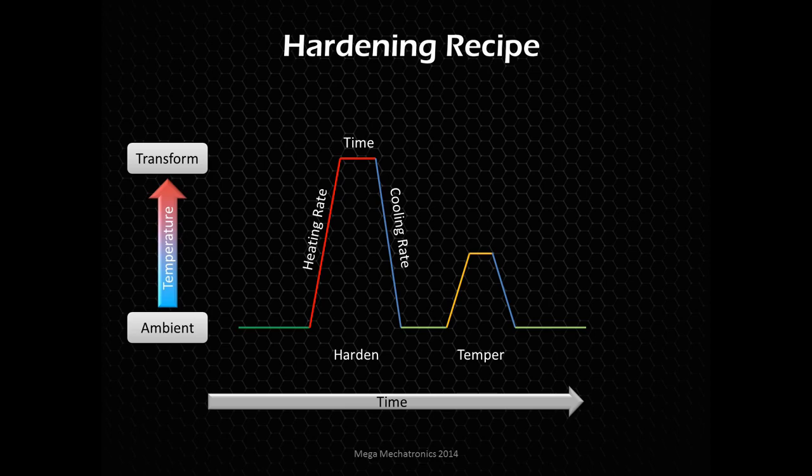The cooling rate is very important. What the cooling rate does, what the quench does, is it locks in a certain desirable crystal structure such as martensite. Different quench media that are used could be straight water, water with additives like polymer additives, oil, and even molten salt.